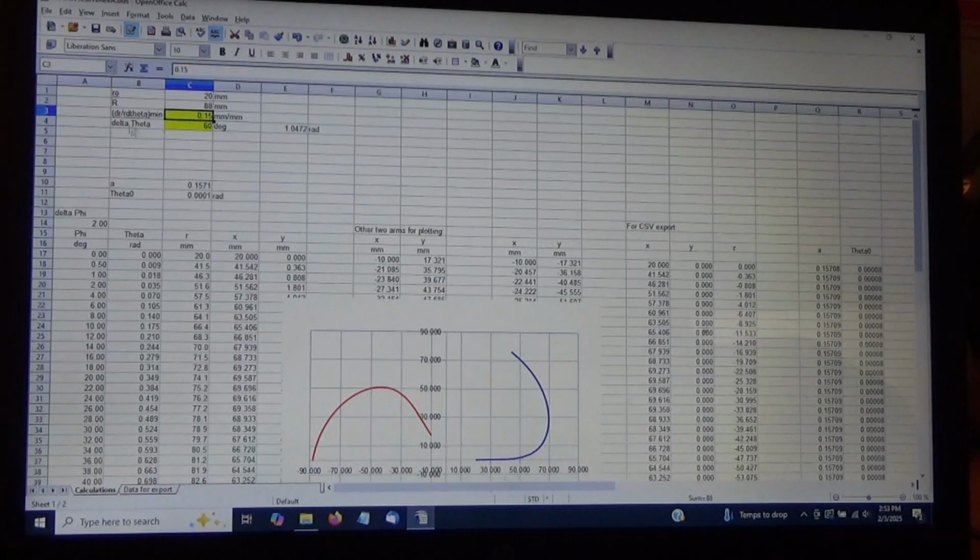And the slope at the extremity, that's change in the radius with radius times the change in the angle, r d theta. So it's going to start out with that small slope, and then the slope is going to increase and increase until it gets towards the root. And delta theta is how much of an angle that this blade occupies. So I've got 60 degrees here. Then I converted that 60 degrees to radians because everything should be in radians.